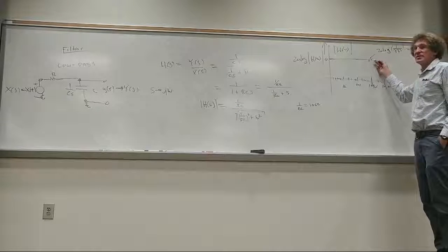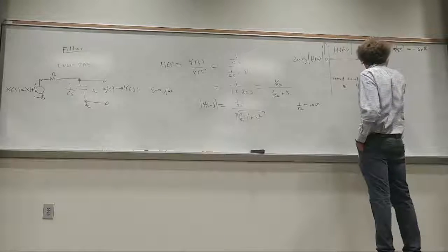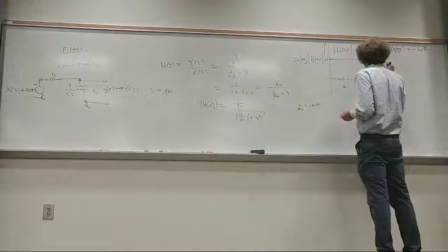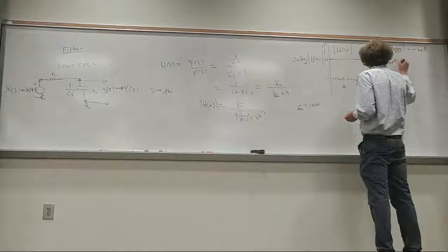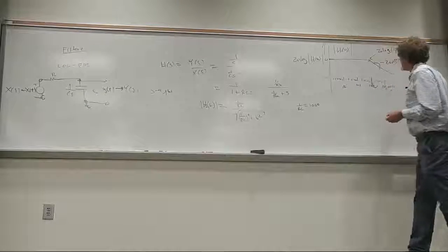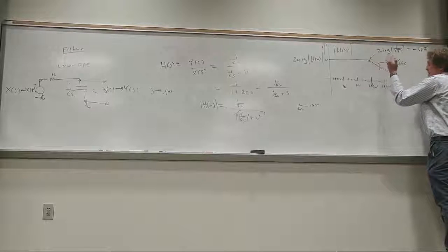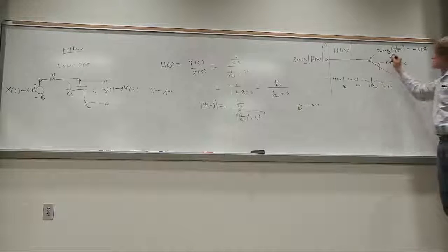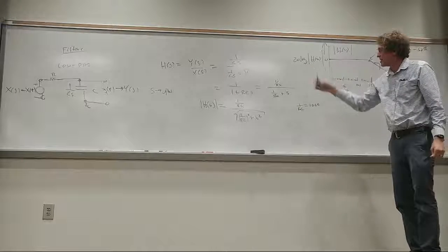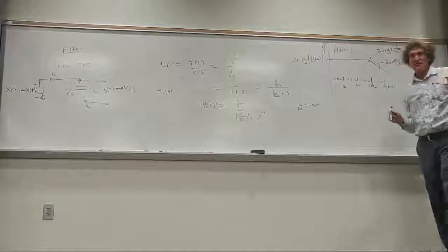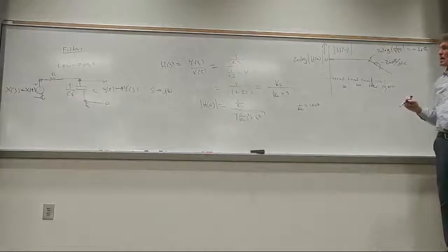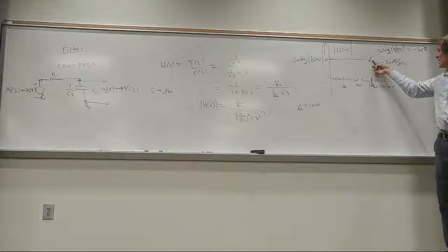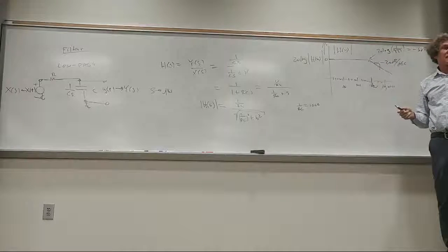Now this is an important frequency because that's literally called the 3 dB frequency. It's the first break frequency. And then after that, this thing's going to keep going down at a rate of minus 20 dB per decade. So from 1,000 to 10,000, it'll drop by 20 dB. And the reason is this 20 out in front. I'm not going to go through the whole thing, but this is basic filter properties. You can build a low-pass filter, and you can choose 1 over RC to be 1,000, and that means this is going to be the actual cutoff frequency, right?